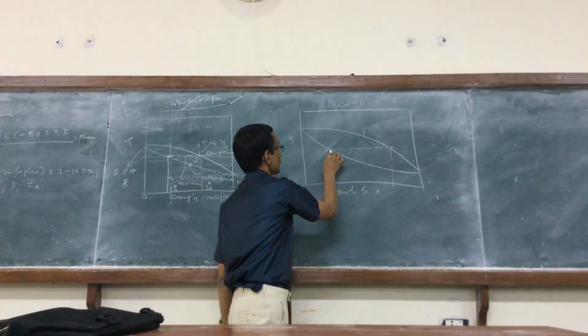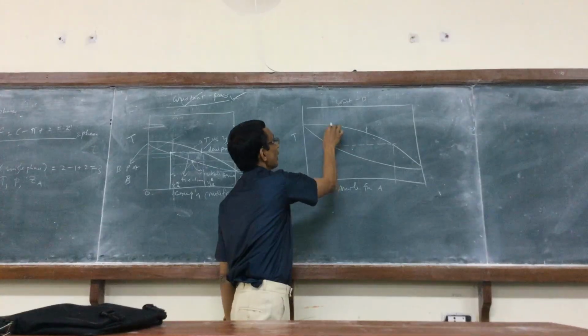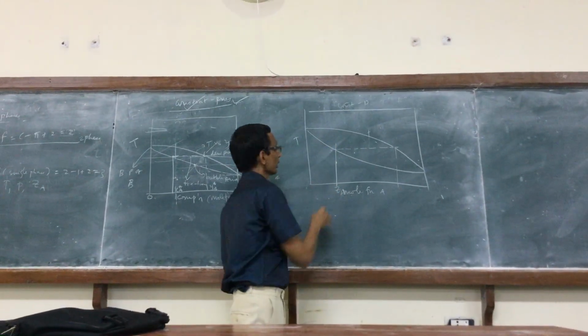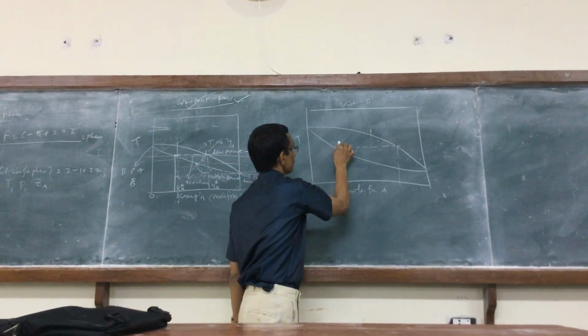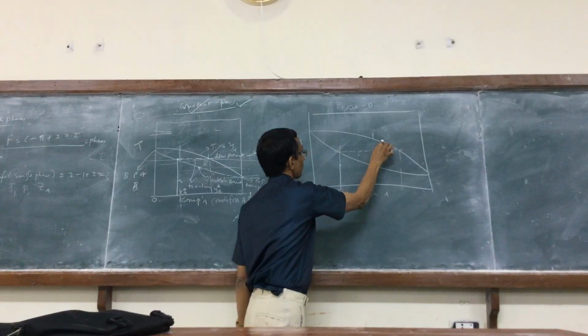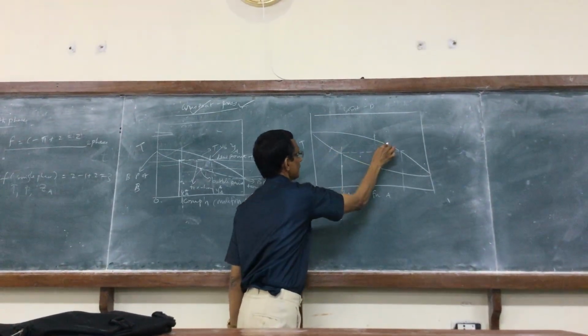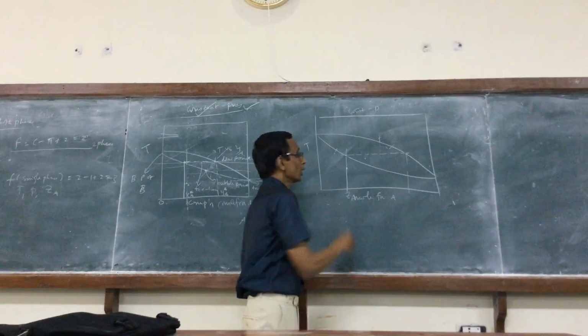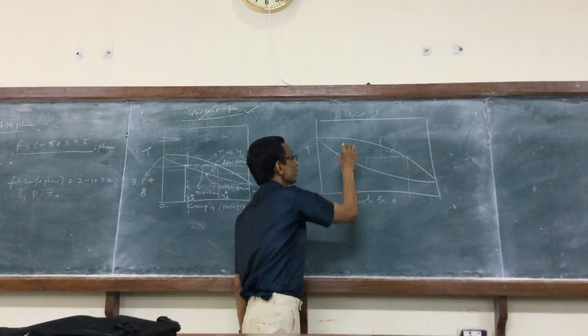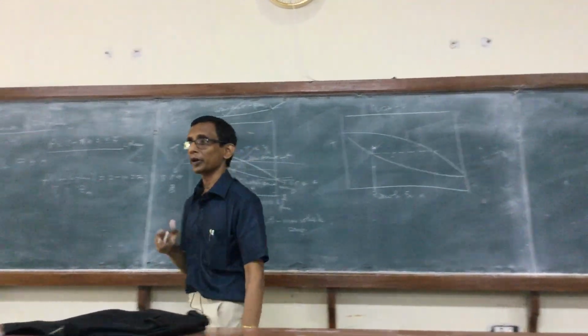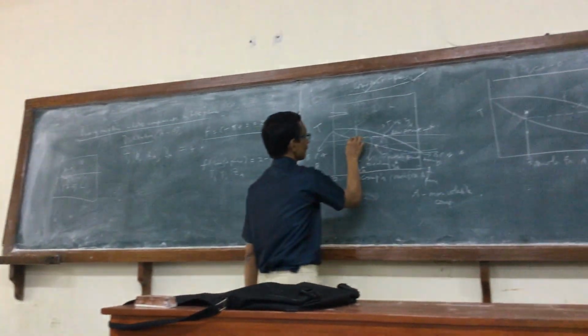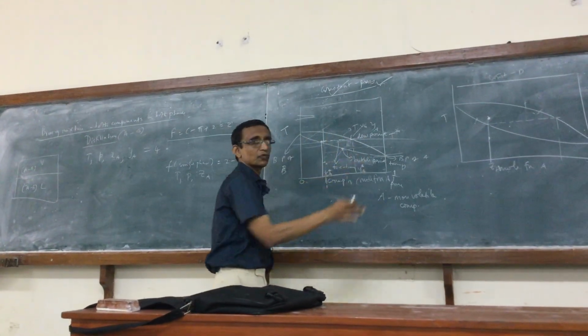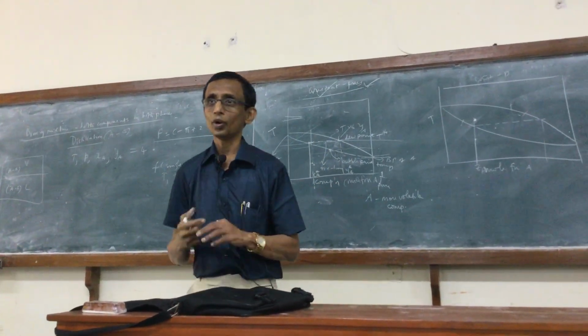Now as I continue at the same pressure, as the process proceeds, this will be the state of the liquid, this will be the state of the vapor. Now the actual point here, from a thermodynamic point of view, is that this is often called a region of two phase, but there is actually no region.